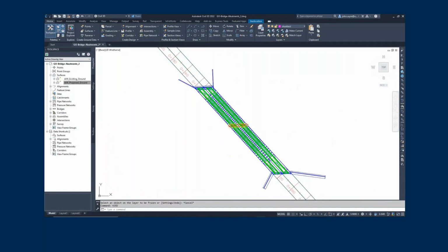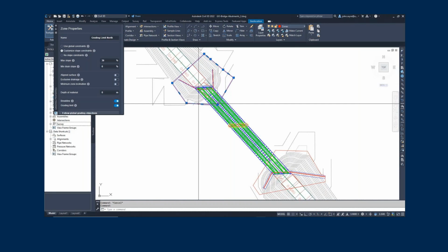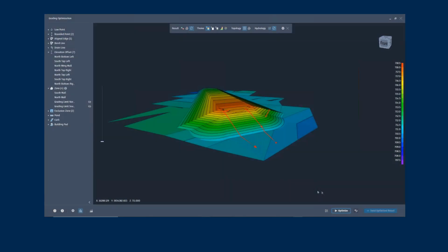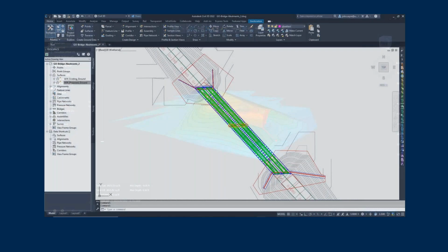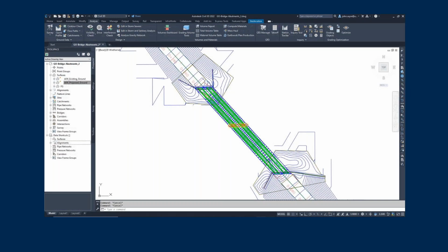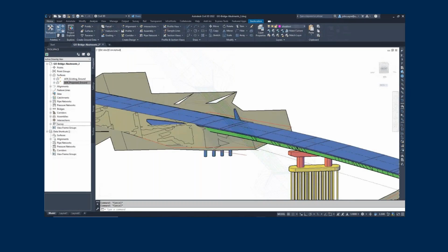This also applies when it comes to retaining walls and stuff like that. So I was speaking to a user this week, and she actually brought up the same thing in terms of how can you replicate the ground behind the retaining walls. So this is how we're going to do it. Okay, so we've got that area, we select it, and we optimize it based on the retaining wall. And if you look there, now it looks absolutely correct.